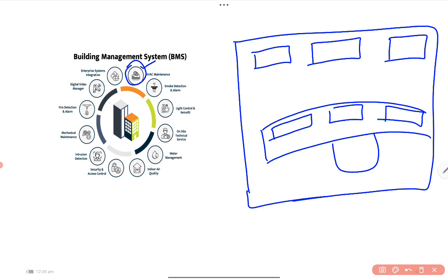So we can manage this HVAC maintenance from the data hall, and it will be managed by this system: what sensors there are, what pressure valves there are. In the HVAC system we can manage cooling. Then smoke detection and alarm. For smoke detection we use the VESDA panel, very early smoke detection system, and for alarm we use FAS, the fire alarm system.